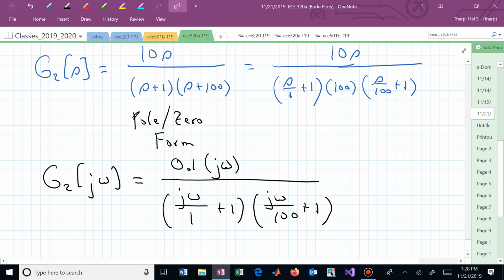And since it's upstairs, it's plus 90. And we just said that the bottoms aren't contributing anything. So what's the phase of this transfer function at small frequencies? 90 degrees. Do you see how you arrived at that? And you didn't even have to use your calculator. You just have to look at that transfer function and you go, got it.